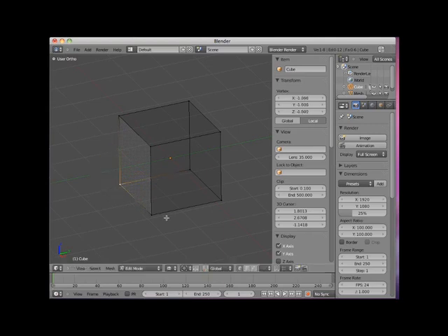By default, when entering Edit mode, Blender places the mesh in Vertex Select mode. The control button for Vertex Select mode is located here on the 3D Editor Viewport header. Notice that in addition to turning the selected vertex white, Blender also indicates the influence associated with this vertex by these yellow lines that fade out over distance.